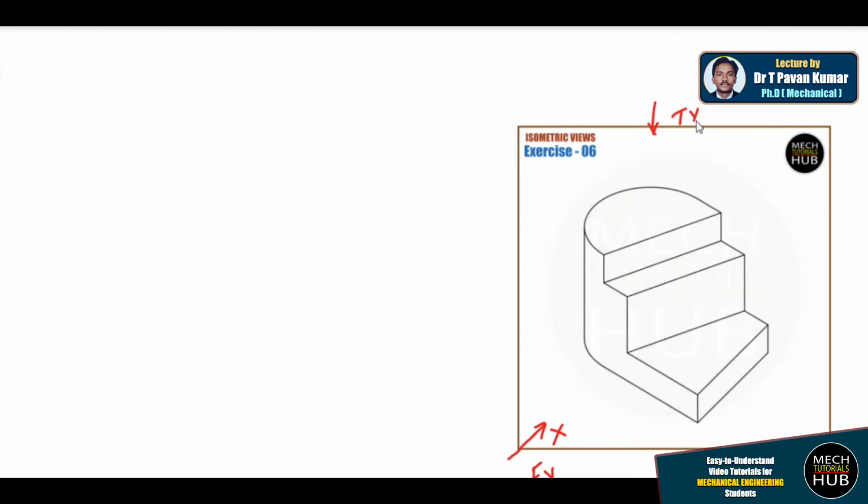Top view position. So when I view from the front, whatever is visible needs to be drawn on a drawing sheet, and similarly whatever is visible from the top needs to be drawn on the same sheet of paper. But the thing is, both the views should align properly. Both the widths should be aligned with each other. That is more important.